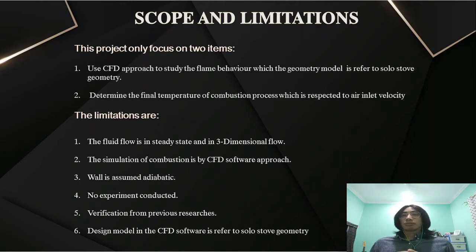The limitations are that the fluid flow is in steady state and three-dimensional, the simulation of combustion is by CFD software approach, the wall is assumed adiabatic, no experiment is conducted, verification is from previous researchers, and the design model in the CFD software refers to solo stove geometry only.